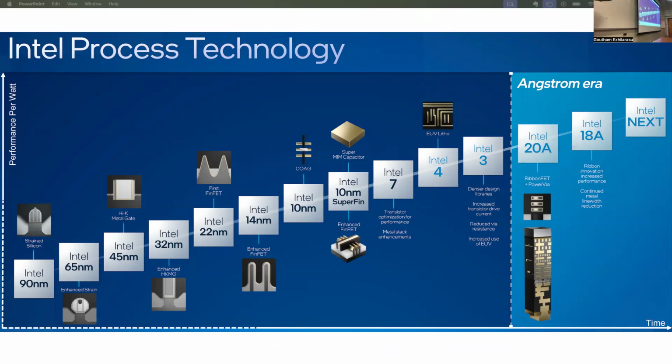Yeah. So it serves multiple purposes, okay? If this is the gate and this is the sidewall spacer, one purpose is to create this kind of profile, correct? The only way to make this profile is using a sidewall spacer, because initially you do a shallow implant, and then you put a sidewall spacer, and the sidewall spacer shadows this region so that when you do the next implant, you can get this kind of profile, right?